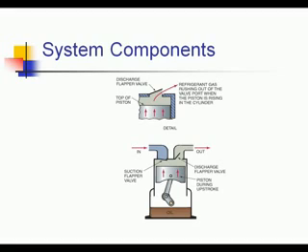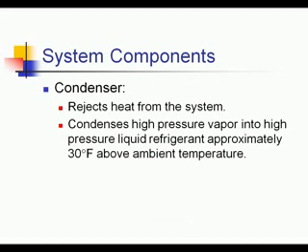Compressors are not meant to run in a vacuum. They don't run under atmospheric pressure. Running a compressor in a vacuum will damage the windings. Refrigerants provide the cooling for these compressors. No refrigerant, the compressor will not cool properly.